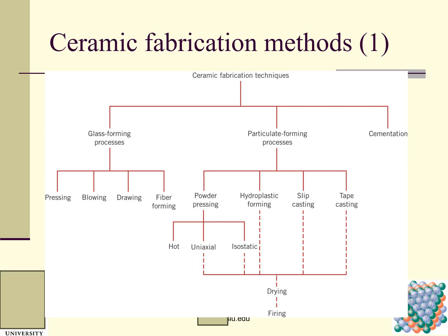So here are the ceramic fabrication techniques, and we talk about how we fabricate the ceramic material. We have glass forming processes, particulate forming processes, and cementation. These are 3 big categories. And within this big category, we have pressing, blowing, drawing, and fiber forming.